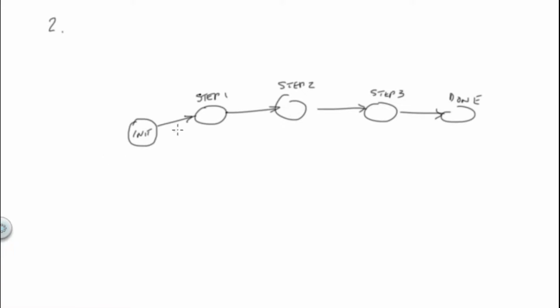By the way, this is kind of like the sequencer logic that we had before, but I wanted to remind you of one thing with sequencer logic, and I did not mention it earlier on. When you have step to step to step to step and then done, like we did for the sequencer logic, if somebody comes in here and stops it while you're doing a step, for whatever reason, you have to be careful about how you reinitialize.